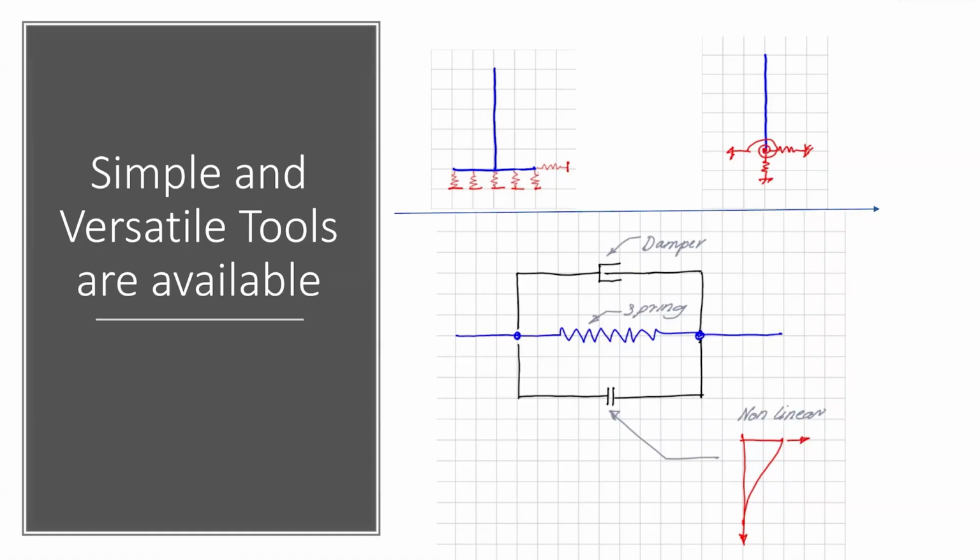If you model the foundation in each direction by a combination of a damper, a spring, and a nonlinear gap or nonlinear element, then you can model all of the complexities that I mentioned, because you can model separation, contact, dynamics, yielding, and this nonlinear soil behavior or nonlinear link. So if you have the data from the geotechnical people and you have the time and the capability, you actually can do pretty much a lot with the foundation and structure.